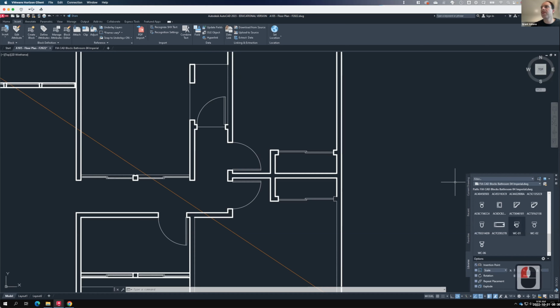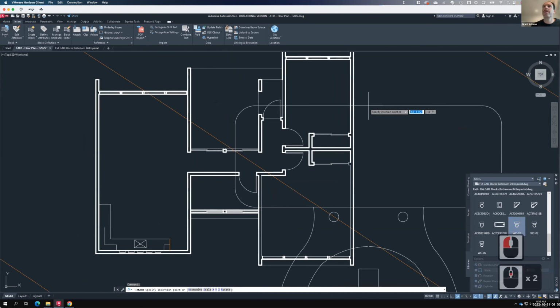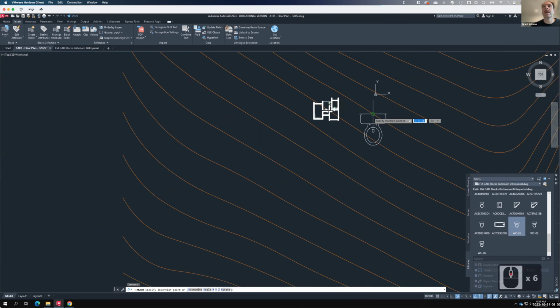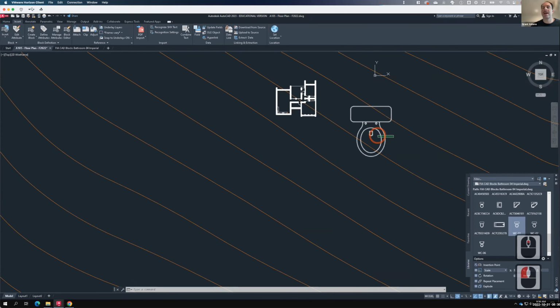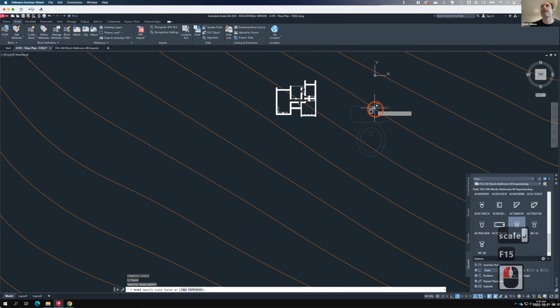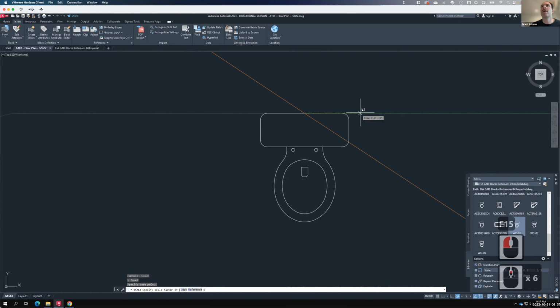And so you can see down here on the right side that there are all the items from that file. So if, for example, I wanted this toilet, right, I can click on that toilet and it's dropping the toilet in. It's obviously not at the correct scale. And this is always the risk when you're borrowing files from somebody else, is that they come in the wrong scale. So we would need to scale this down. Let's scale it. And what we need to kind of know is what one of the sides would be.